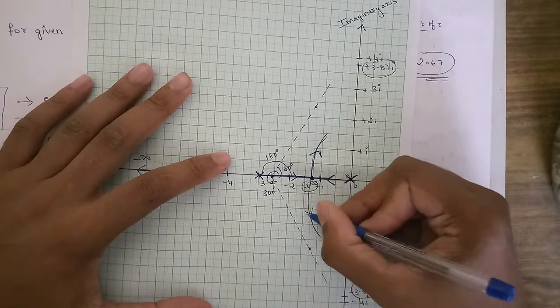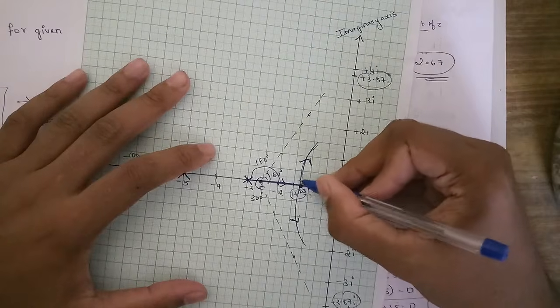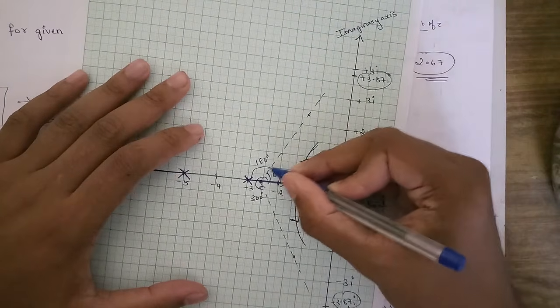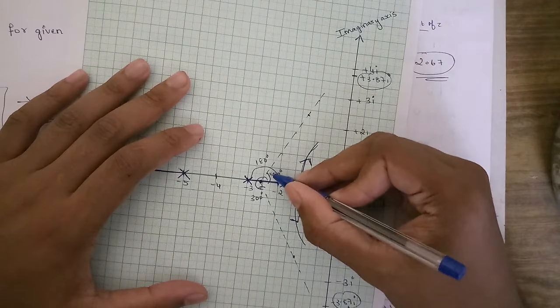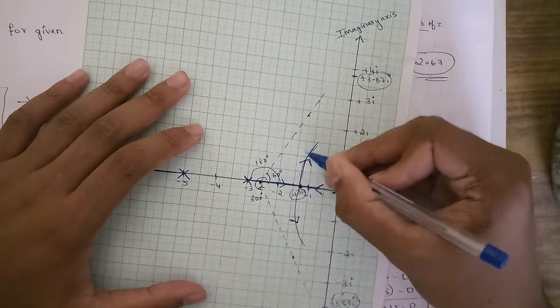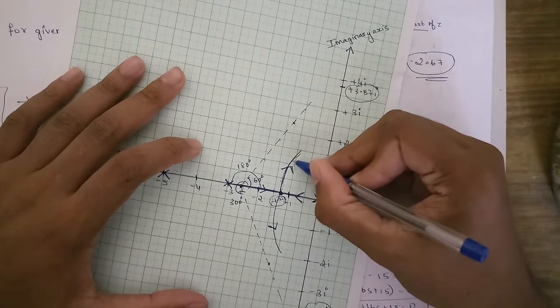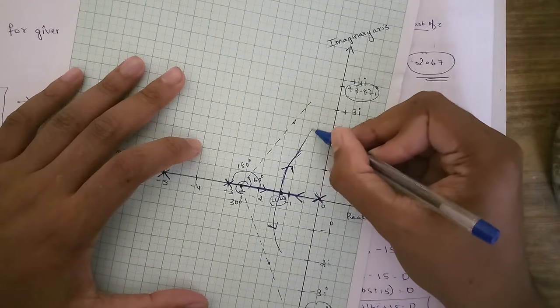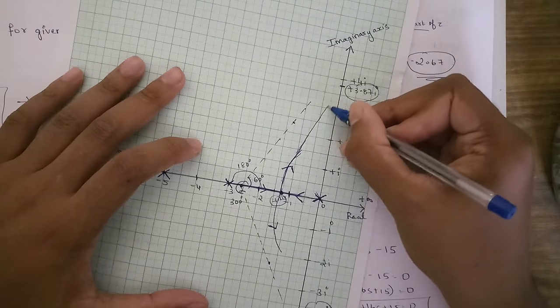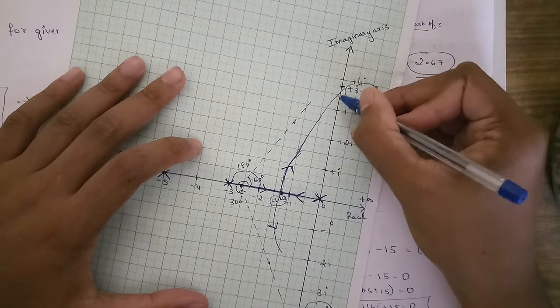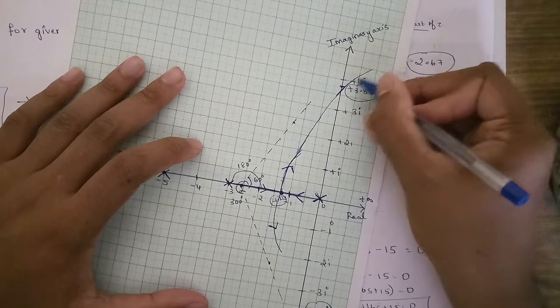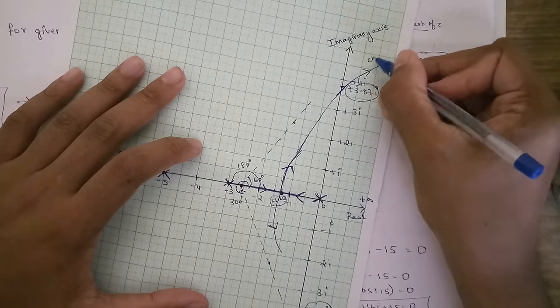In this direction. And now this root locus bends at an angle of 60 degrees. Since we have an angle of asymptotes of 60 degrees with the line of asymptotes, it would be following that line only, and it would be bending in the same line. It would be moving towards the point of intersection, that is plus 3.87i, and it would be approaching infinity.